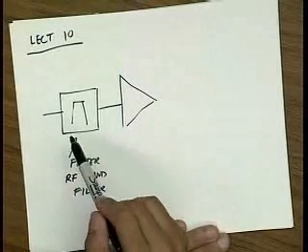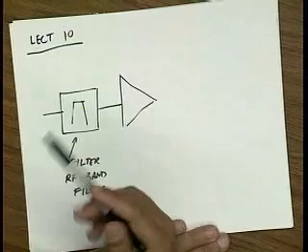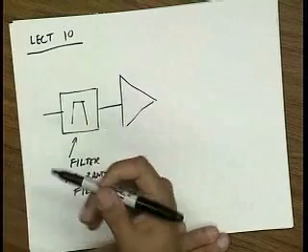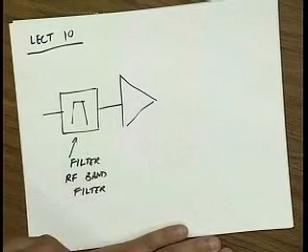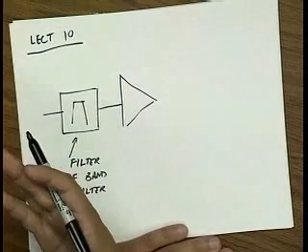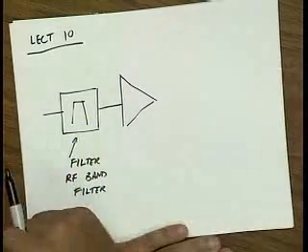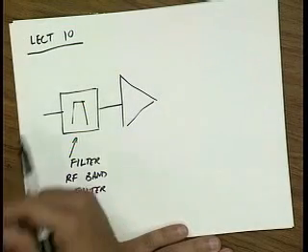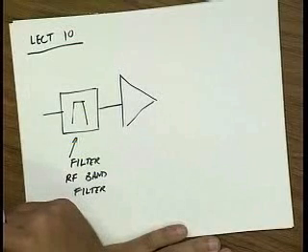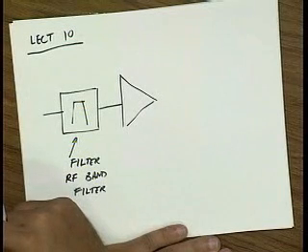But I can have in-band jammers. And as we've talked about throughout this course, in-band jammers are quite common. There are other people sharing the spectrum with you, and the signals that they're transmitting could interfere with the signal that you're trying to receive. So you still have a situation with jamming. Other question? Wouldn't putting a filter ahead of the LNA also introduce more noise into the system?